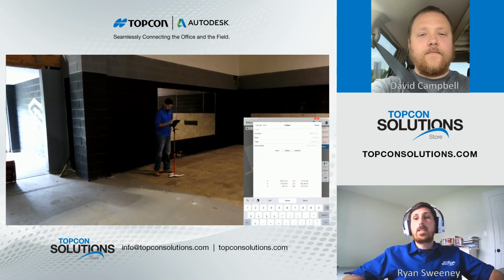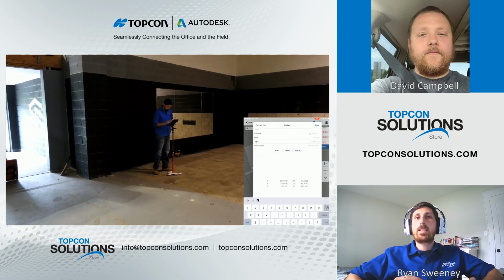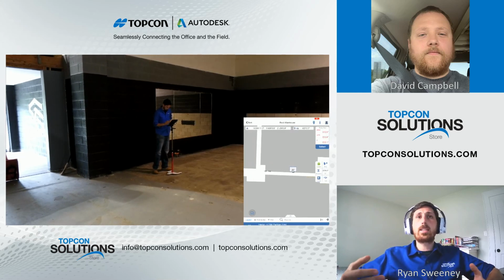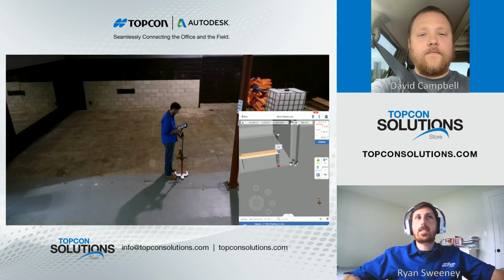The nice thing about it too is you can also use it for as building. So as you're walking around your job site, if you need to take a shot of a specific thing, you can just hit that nice easy collect button, and you can change the name of the point. You can set them on different layers and point types. So that way everything stays nice and organized. And as these files get worked on and saved, they'll be automatically uploaded into the BIM 360 cloud space. So everyone in the office will have access to these points that you shot and laid out.